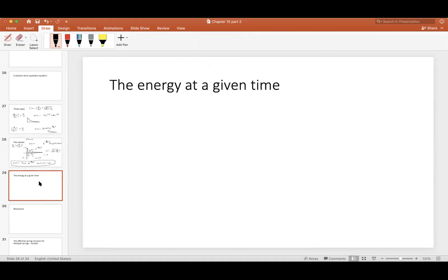And the energy here, your book takes a cheat. I'm going to cheat on it too, because I don't want to get into it. We'd be here for another hour. But basically, if you can say that k over m is much, much greater than beta over 2m squared, then you can assume that basically the amplitude is x max times e to the minus beta over 2m times t.